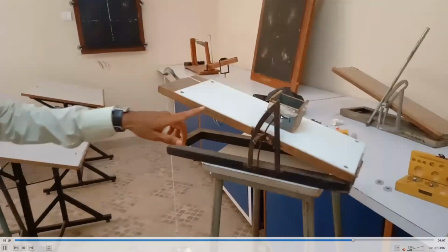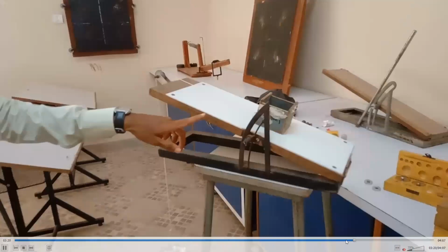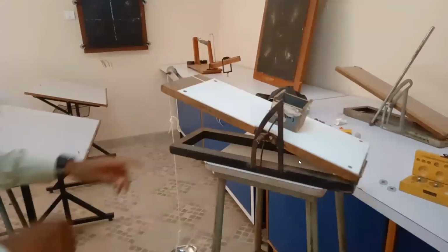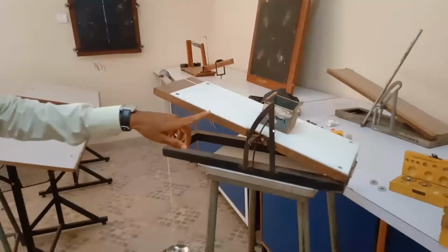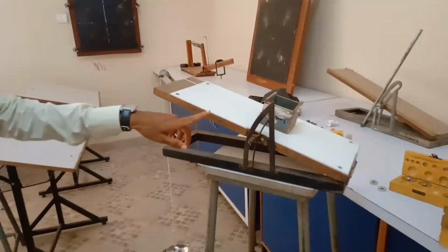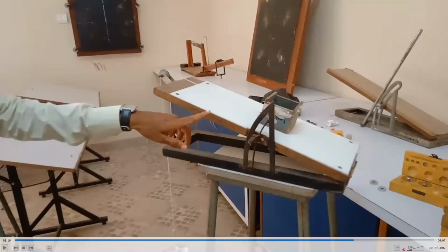Okay, so this is the impending motion. Again, observe. At this condition, you can observe the slight movement of the box. It is not completely moving. That means the block has reached the limiting condition for equilibrium, and it is the Fmax value for the frictional force. This is called the verge of motion.